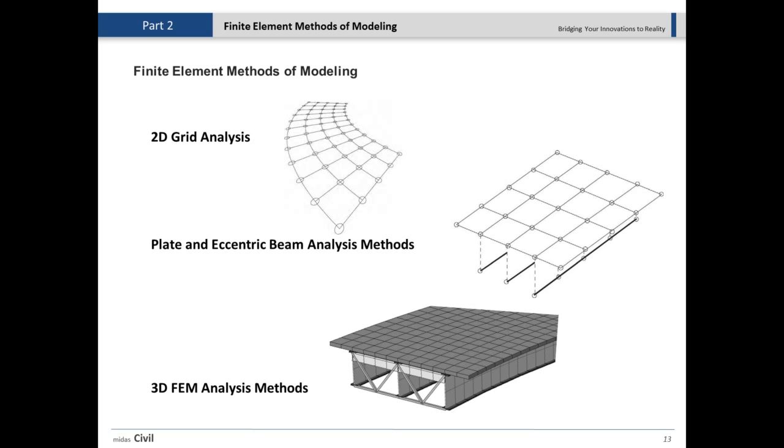So the most accurate way will be modeling a 3D finite element model. We can use a beam element or plate element in 3D and then see all those effects. So we talk about these, and I told you what options are available in the software, and what are the methods of the modeling of these.